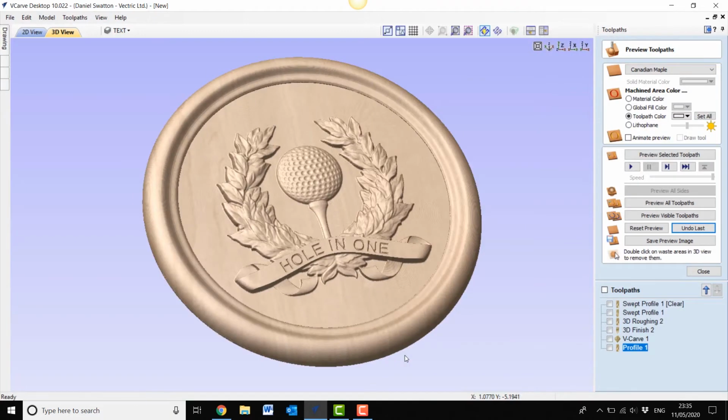And then, of course, we've looked in the software at the ability to use the easy assembly tools such as add and merge to create a number of files when you compile them together in the particular component. We've got an instant 3D view, so it enables us to feel comfortable about what we're going to actually start creating toolpaths for. And one thing that is particularly exciting is the molding toolpath, since it builds the 3D shape from essentially 2D geometry.